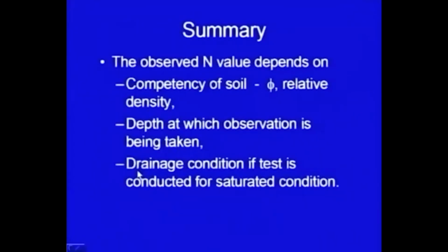The third condition is drainage condition, that depends on what kind of soil is there. Is it fine sand? Is it coarse sand? Is it silt? Is it clay? Something like that. So, drainage condition, if the test is conducted for saturated condition. So, obviously, this will be applicable only when the soil is completely saturated.